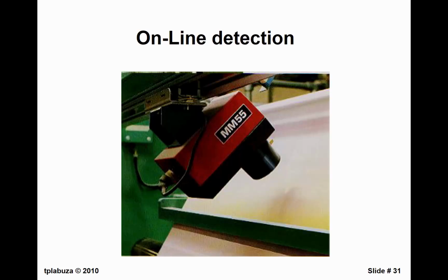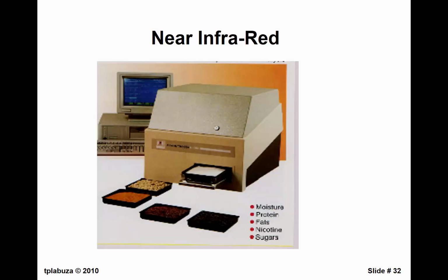Now it's completely automated with near infrared. You can buy these near infrared instruments, and they say they can measure moisture content, fat content, and protein content. Well, you just can't take an odd sample and put it in there and get good numbers. You have to have a standard for each of these. It uses different wavelengths for water content, for protein, and for carbohydrate. It's a good quality control tool once you have precision from comparing it to other methods.